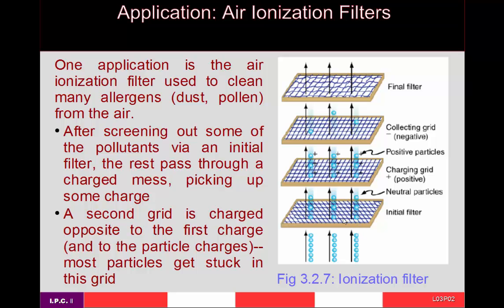In fact, the typical amount that I've seen quoted is about 85% gets removed. That's pretty good, but if you start with, let's say, 100,000 particles per cubic meter, then you actually have pretty clean air already. In fact, they make clean rooms that have a 100,000 rating.